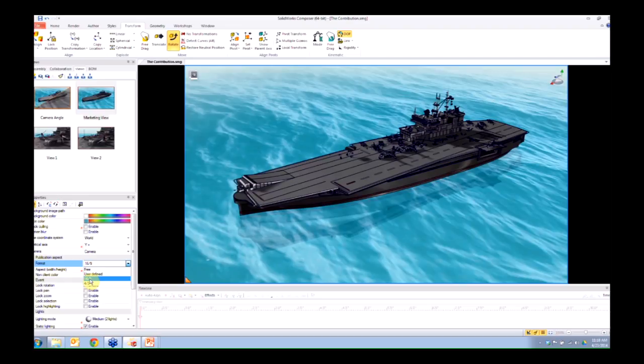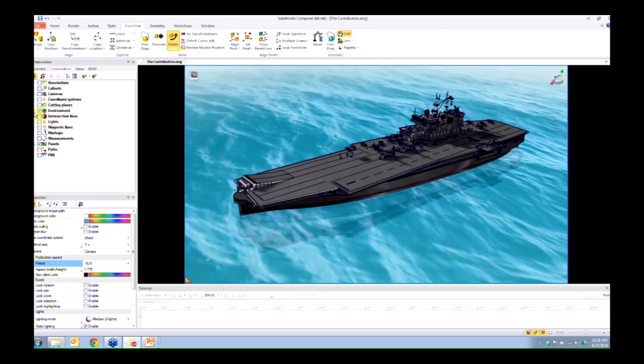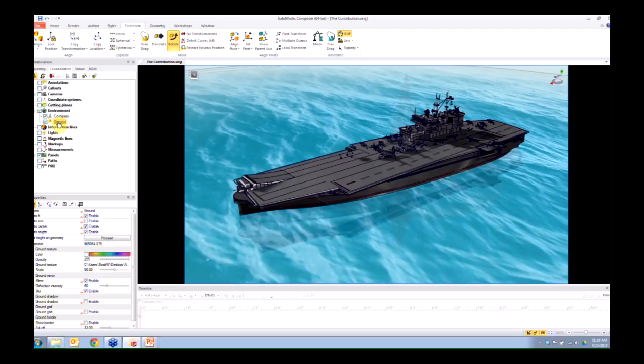Third tip here, just so I cover all the bases, is the ocean, the water, the reflection and all that. So what's going on there is in my collaboration tab I have what's referred to as the ground. It's under environment, ground. So I have the ground turned on. You just click it here, and it turns on. Control-G will also toggle that off and on.